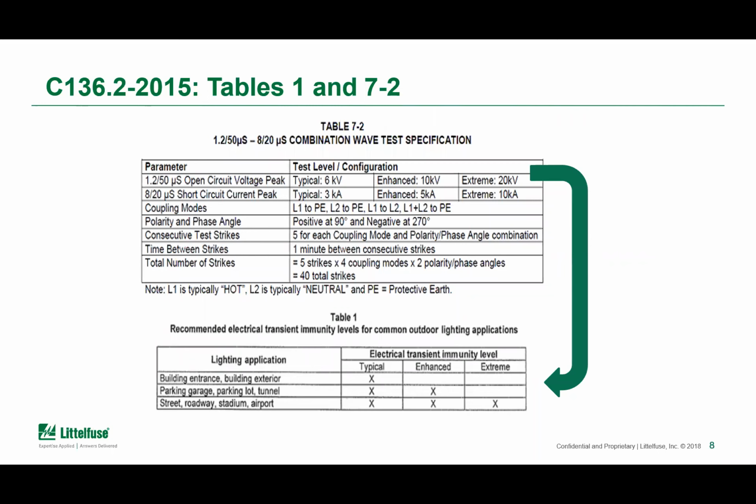So, say for a 40 kV device, it will survive 10, 15, 20 pulses at 10 kV. It'll survive maybe 100 pulses at 1,000. But if you're at a 10 kV device or a 6 kV device, you're going to be a fraction of that as far as reliability is concerned. So the real key to using a higher-rated device is that you increase the life, reliability, or pulse cycle capability of the device that you're using to protect your fixture.